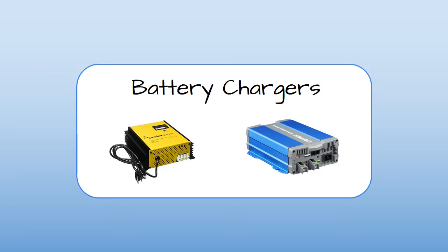They can be used to charge batteries that can be switched on when the power goes out, or you can take the batteries to remote locations to power inverters. Even though you are charging the batteries at 12 or 24 volts, you can disconnect them and then take the fully charged batteries on the road and connect them in 12, 24, or even 48 volts. One thing to note is that the output current in these chargers is DC.